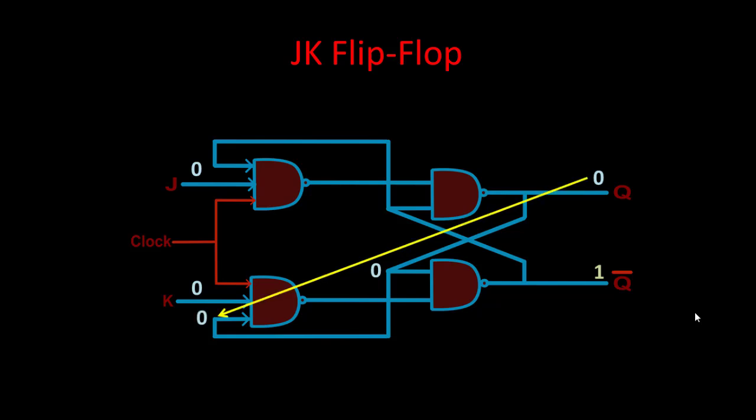So both of them become 0 0 because of the feedback. Similarly, this 1 comes at the feedback of the upper output NAND gate as well as the input NAND gate. Now because in case of a NAND gate, even if a single input is 0, output becomes 1, the outputs of these NAND gates both become 1 1 simultaneously.